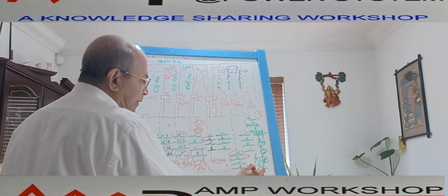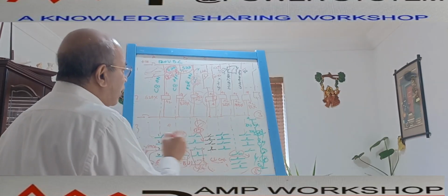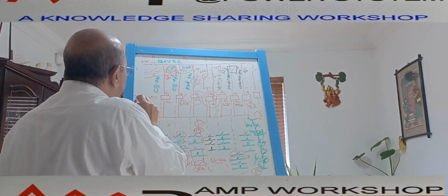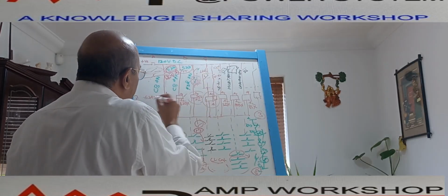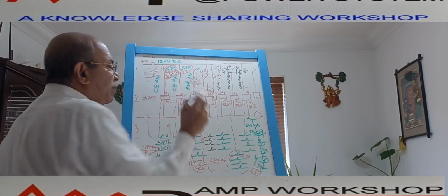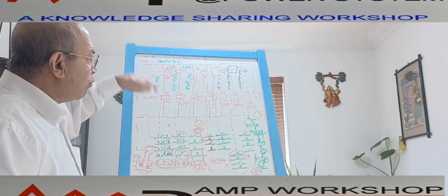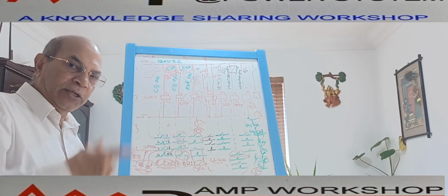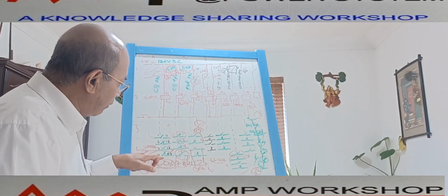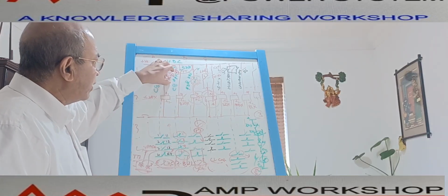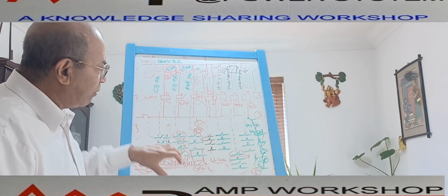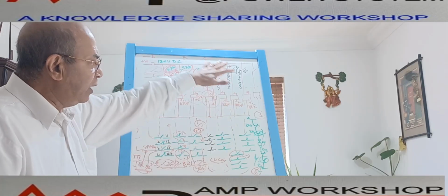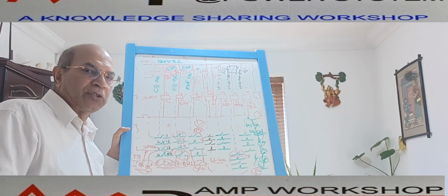So suppose this is page number 8. In this page, I go to row C and vertical column 2. I come this way, and in this location this 52B is there on that drawing. So this way cross reference is used to identify where the auxiliary contact is coming from, and where this output auxiliary contact is going. For a master contact, where it is coming from, and for the auxiliary contact, where it is going and in which circuit, we clearly mention over here, and this way the breaker auxiliary relay scheme is made.